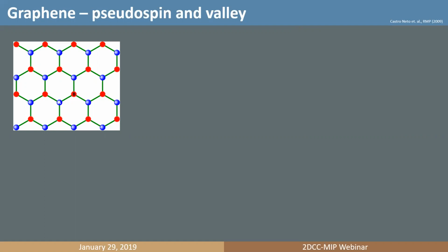Now, before we go into what strain is, what strain does, and how to engineer such a state, let's do a quick one-slide summary of graphene electronics. So graphene is formed when carbon atoms set themselves in a hexagonal lattice. And if you stare at this lattice for a while, you will realize that not every atom is equivalent. If you sit on an A atom, you will see bonds at 10 o'clock, 2 o'clock, and 6 o'clock directions. Whereas if you sit on the B atom, then the bonds are at 8 o'clock, 4 o'clock, and 12 o'clock directions. So there are two inequivalent atoms.